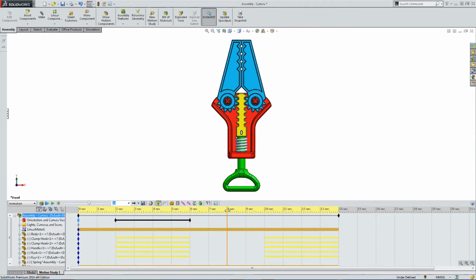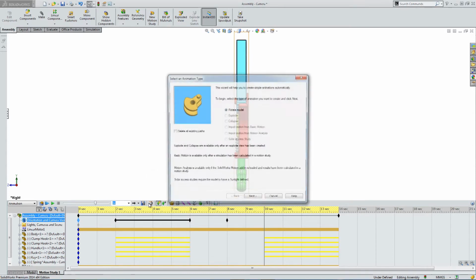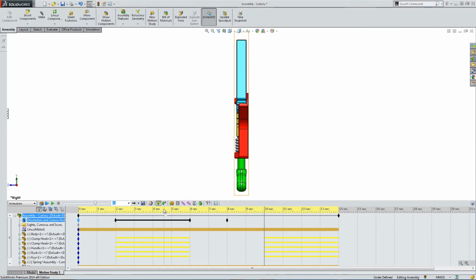Okay, so now let's try adding some rotation. At 8 seconds, we're going to start a 360 degree rotation of the camera. So we add another keyframe. Nothing's happened between 6 and 8, so there's blank space. Now at 10 seconds, let's do a quarter turn. We can add the keyframe. We can actually add a rotation using the animation selector, sorry, the rotation wizard tool, but we're going to do this manually.